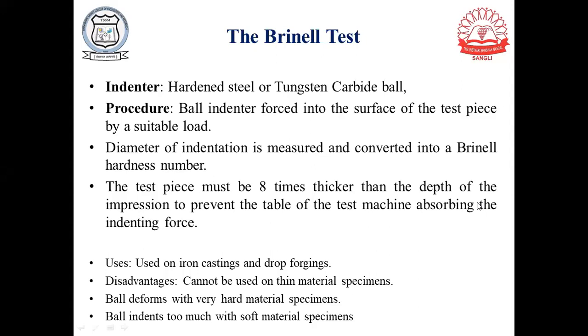Because if your component is not 8 times thicker than the depth of the impression, then whatever load you are trying to apply on that specimen will be transferred to the table of the machine. Would that be okay? Can anyone answer me?